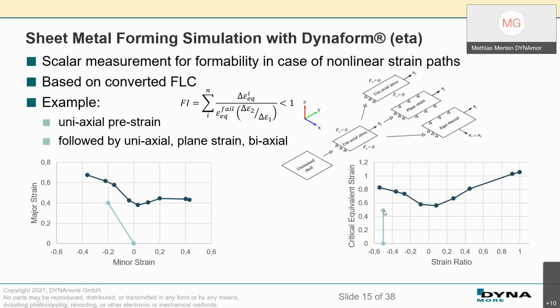According to this simple formula, you can calculate the formability index and estimate it roughly at 0.6 or 60%. So this means at this point you have 60% of the formability of your material consumed for that first process. From that you can conclude, and this is what I did with Excel in the background, that for the rest of the forming you can still use 40% of the formability.